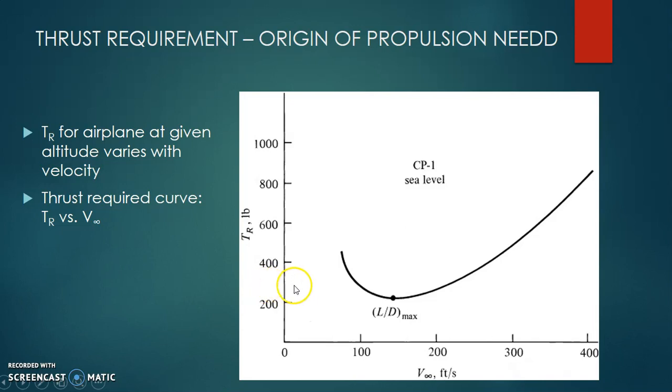That's where the thrust produced is good, but the required thrust is minimum. Never get confused about the axes of these. It is TR, which is the thrust required curve. It is not TD, which means the thrust that you have been asking for from this aircraft engine is now going down as the velocity increases.